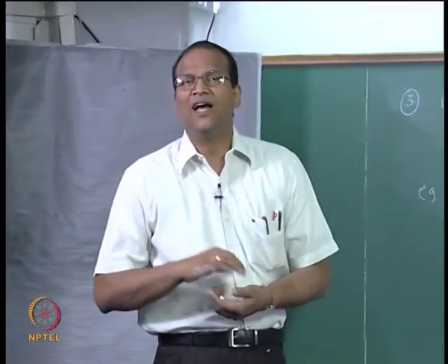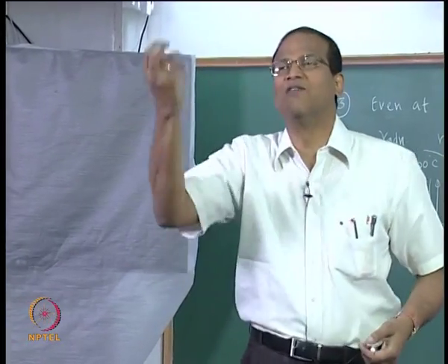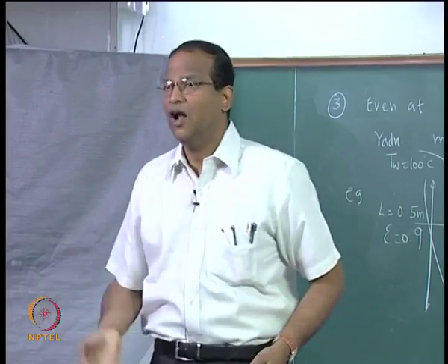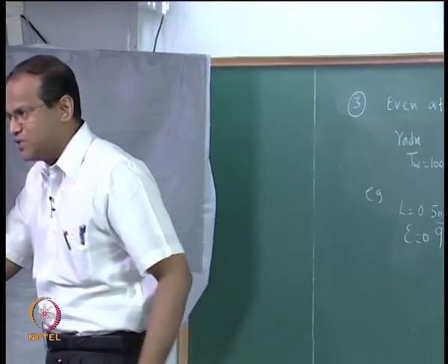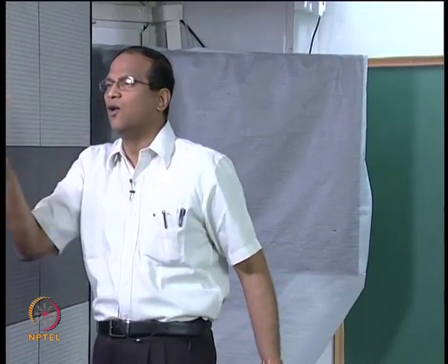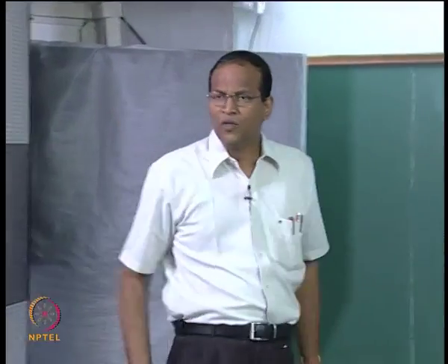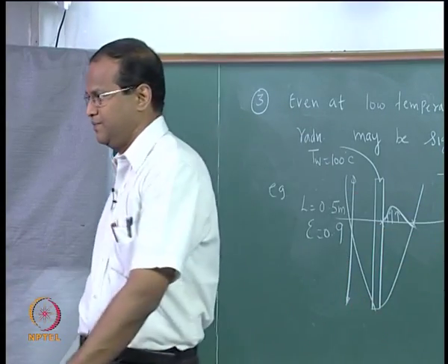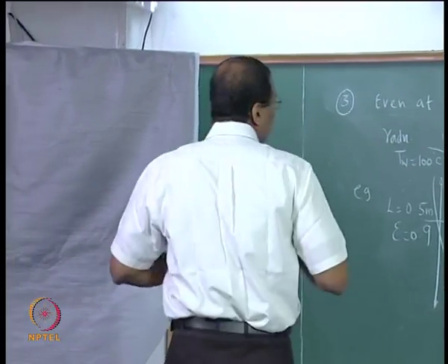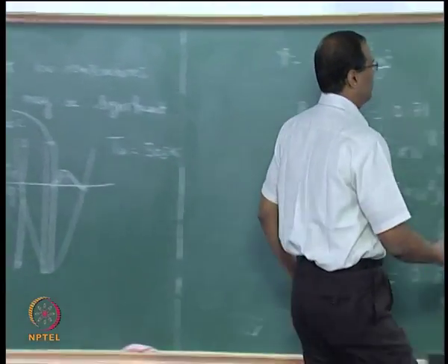So as engineers, you must have a feel for how much flux can be dissipated using natural convection. The ballpark figure is that more than half a kilowatt per meter square you can't do. You can convert it into equivalent centimeter square, millimeter square and work out the numbers. Okay. Now the beauty here is, what will be the Q radiation for this problem?